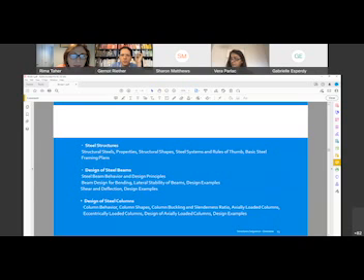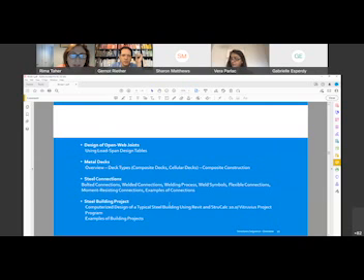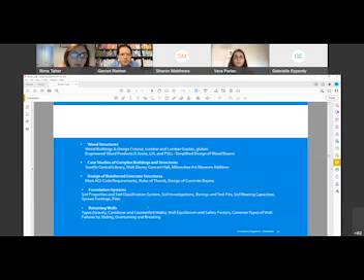After we are done with the design of steel beams and steel columns, we talk about steel connections and open web joists. I show the students how to size open web joists using the design tables that are provided by the Steel Joist Institute. We talk about metal decks, structural steel connections, and then we work on that project.